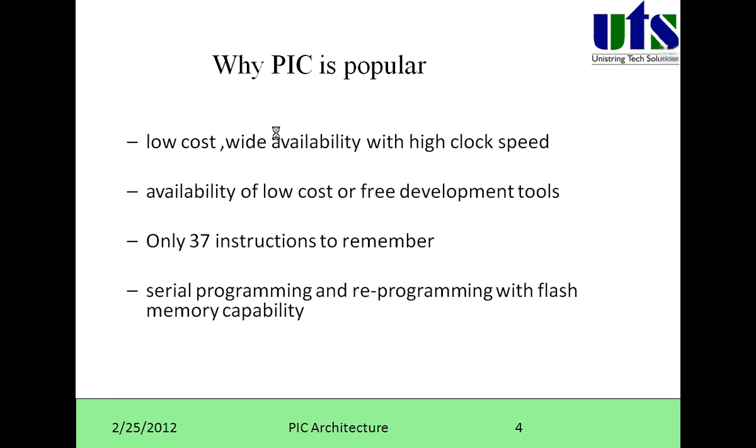When coming to the 8051, if you want to program an 8051 microcontroller, we need to remove the IC from the application board and place it in a separate 8051 programmer. After programming, we have to place it back in the application board and then execute it. It is not like that here. The PIC IC stays on the application board, and we program it through a serial programmer, that is, serial communication.